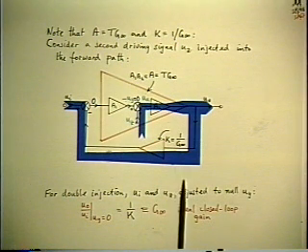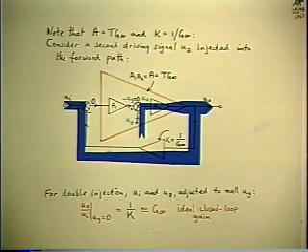Now you see how this last calculation formalizes what you normally do, as we went through at the beginning of discussing the feedback calculation. The difference is that the way you normally do it, you simply assume the error signal is 0. This way, you actually make it 0, and you calculate exactly the g infinity.